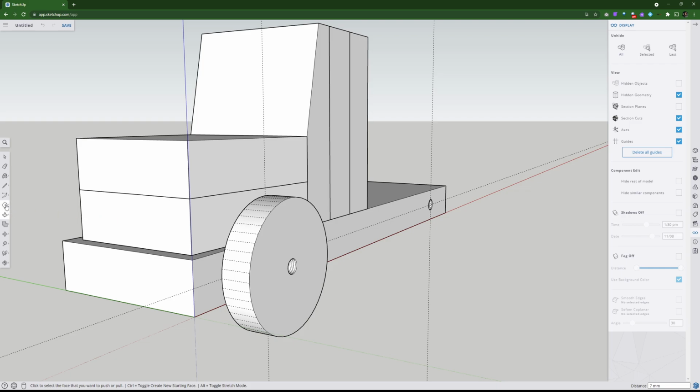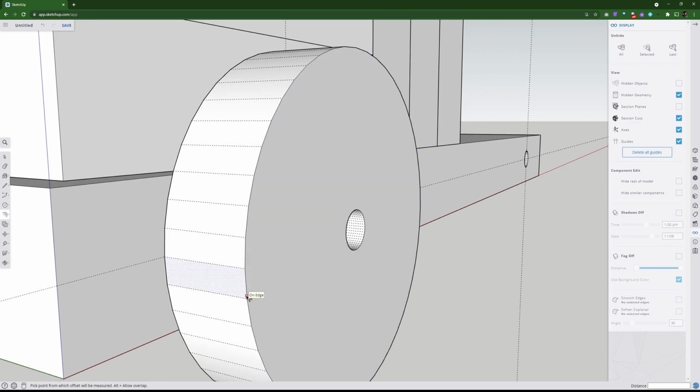So I'm going to take maybe my offset tool. Let's have a look here. So there's a tool down below, and the push-pull called offset. And I've got to do a little bit of math in my head now. It won't be that hard. I'm going to come from this edge. So the edge is all highlighted, right? So I've hovered over there. I'm going to click once. Do it again. Click, and I'm going to drag it in.